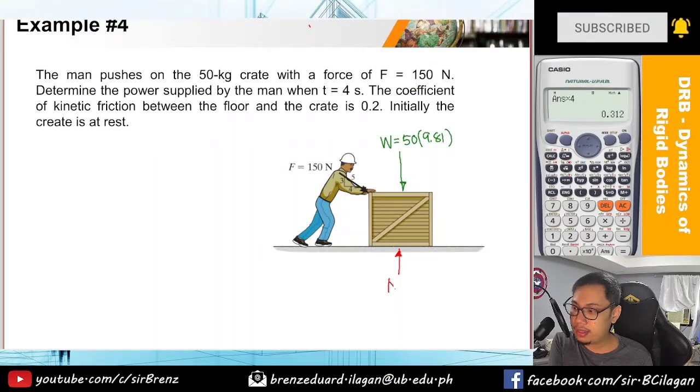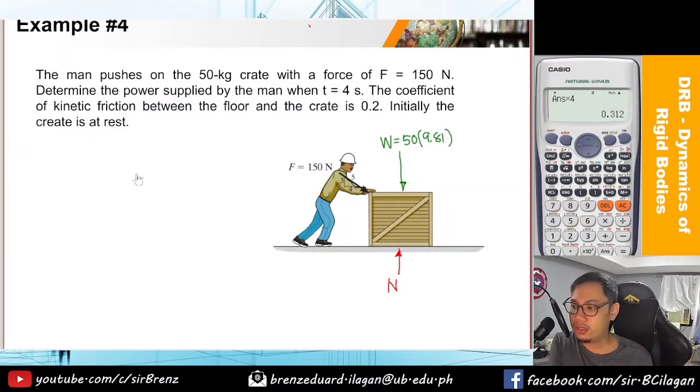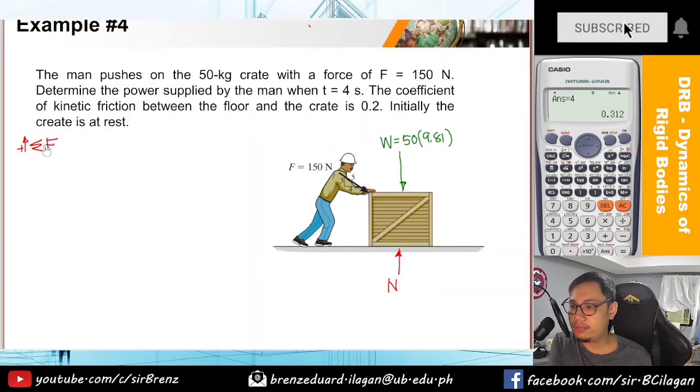So with that, let's solve first for the value of N. To solve for N, we can take the summation of forces in y equals 0, assuming upward direction as positive. So we will have N equals, pareho naman pababa na yan, yung y component is pababa, 150 times 3 over 5, plus 50 times 9.81.